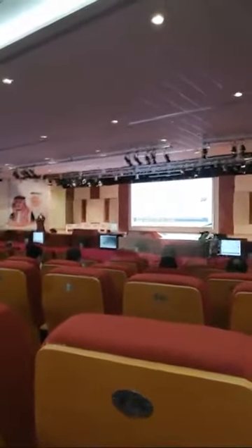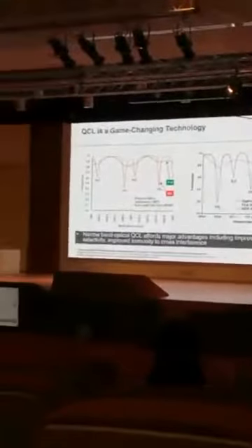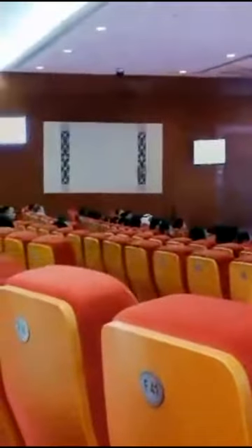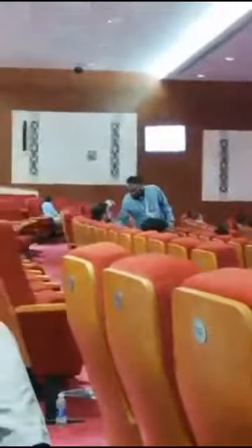How precise this measurement is. Now, the comparison graph that you see over here is a comparison of an industrial grade FTIR analyzer and an industrial grade NDIR analyzer. You can see sensitivity is far better than some of the conventional analyzers that you have. So this enables us to minimize the calibration required for such applications.